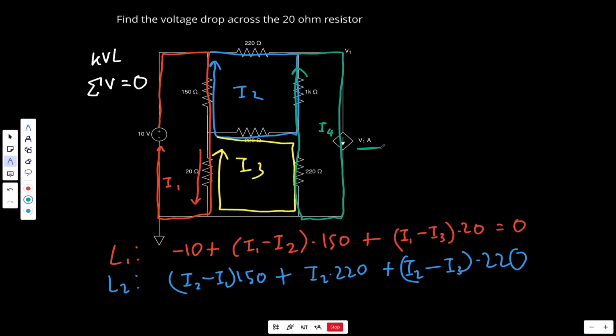It's actually going to be the magnitude of V1 amperes. But in order to get V1 amperes, it's not that simple, because we need to take the voltage drop from this little resistor over here and then take it from 10, because we're going from 10 to some voltage drop here. This is our voltage drop to V1 and then ultimately to 0. So that's kind of like the order in which we're going in. So we need to find this voltage drop and subtract it.